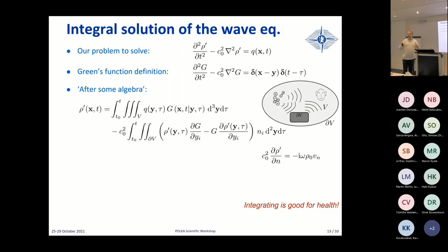You had the best large eddy simulation that gives you the Reynolds stresses, the non-isentropic terms, and everything. So the right-hand side is considered as given to you, and the question is, okay, nice, what is my acoustic field now, anywhere in the propagation medium? It's good to have this solution because then you can combine the solution for your Green's function and your initial problem.